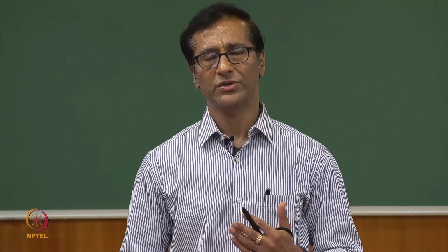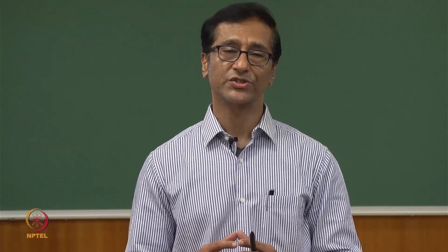If I try to express it in another term, fatigue occurs in practically all mechanical units, leading to localized progressive degradation. Here I am again emphasizing that it is localized, the reason being that asperities are localized, where asperity to asperity contact happens, that is a localized contact. So, in this course we are thinking about that localized progressive degradation that eventually leads to the mechanical unit breakdown.